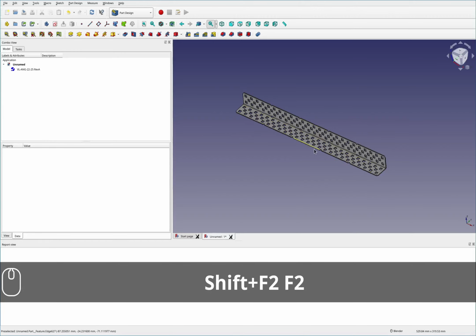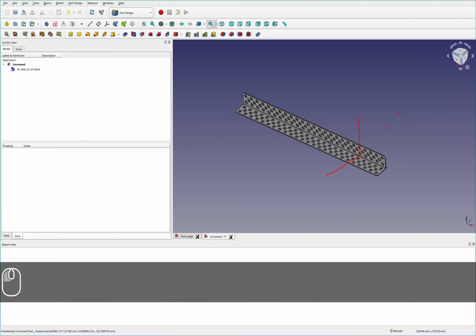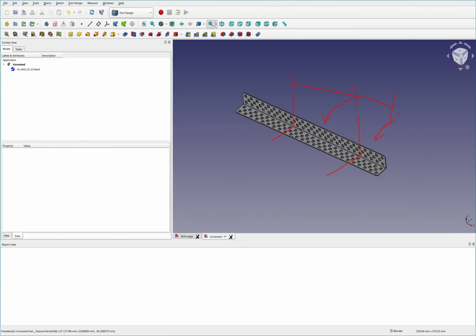So you could purchase this part from Vex, and then let's say, for instance, you wanted to cut it here. And that's something that you could do, right? So you'd be cutting it here using this amount, and then, for instance, cutting it here and using this amount. So we need to be able to define a starting cut distance here and an ending cut length, so that you could cut it to any particular distance in between.